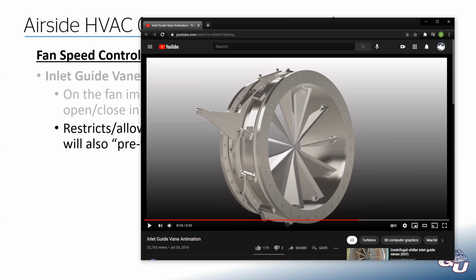So you might have noticed that with those fan impellers, the air actually has to change direction. So it goes into the inlet, but then it has to go outward radially to get to the impeller where the impeller is spinning. What this does is as the air moves through these blades, when these are partially closed and they're at some angle, that will start to pre-turn the air in the direction that the impeller is spinning.